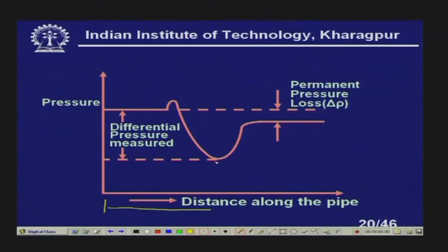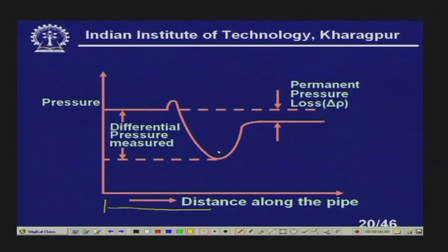So, the wider the pressure loss, if it is temporary, that is good for measurement, because the sensitivity of our instrument will be higher. The pressure drop or differential pressure should be higher and higher, because our input is the flow and the output is the differential pressure. So, if differential pressure by flow is higher and higher, obviously that is better for us, because the static sensitivity will be increased, right.